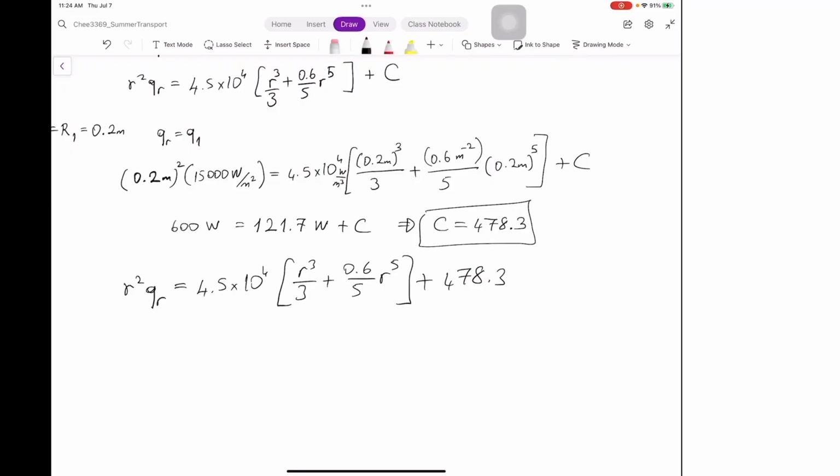It's not going to be useful because it's asking for the outer surface temperature, so we don't know it. It's going to be really difficult to find any constant after taking another integration by writing Fourier's law. Instead, I can just write the heat lost from the outside surface and equate it to Newton's law of cooling, and it's going to give me directly the temperature itself.